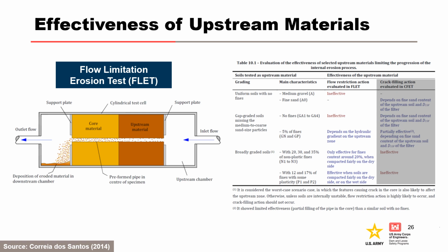For tested upstream materials, soils with plastic fines appear to be associated with higher likelihoods of being effective in restricting the flow than soils with non-plastic fines. The finer the soil, the higher the likelihood of restricting the flow. This trend may not occur on upstream soils considerably coarser than those tested, in particular in soils with high hydraulic conductivity and that are unable to sustain an open pipe.